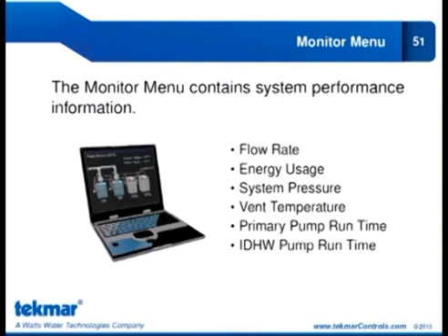Also, the straight pipe distance that you're going to be compatible with on either side. And as I mentioned, rangeability, because we're talking about boilers, depending on where you're locating it. If you had 4 boilers, like some of your examples, and you're measuring a single flow, you're going to have to turn down potentially to 16 to 1. Not many meters can do that.